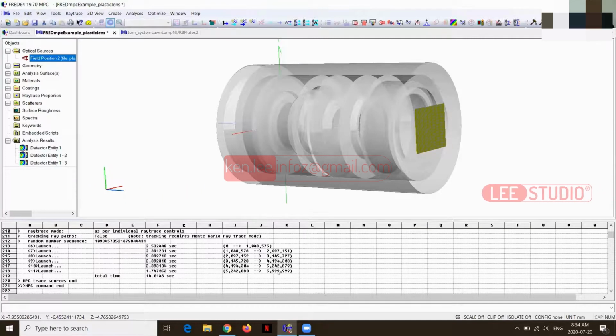Tom, a question. I think that there should be way more rays. Is this true? Because I think on each surface there will be a bounce back. Is this right? Yes. In this case, this is being set up to run in Monte Carlo mode, which means there's no extra rays being created. This is just a simple test of 6 million rays. In the slide I showed you, we used 100 million rays for those times, 200 seconds and 7.5 hours on the CPU. So yes, you'd probably need much more than 6 million rays than this simple example.